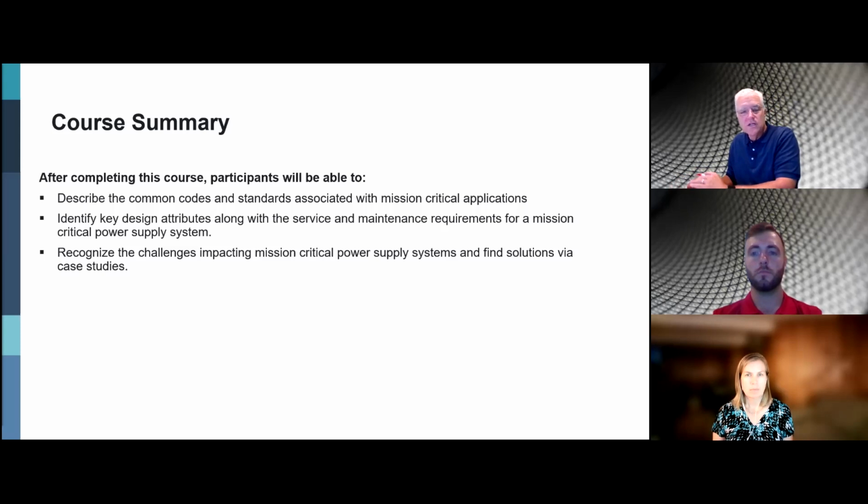And finally, we shared Alberta Children's Hospital applying a separate facility designed for their 3 2-meg units, supplying the hospital at a medium voltage 4160, then stepping down the voltage at the hospital's main campus. This remote facility improved overall performance for the hospital in means of sound and vibration reduction, improved cooling, and serviceability of the power supply system.